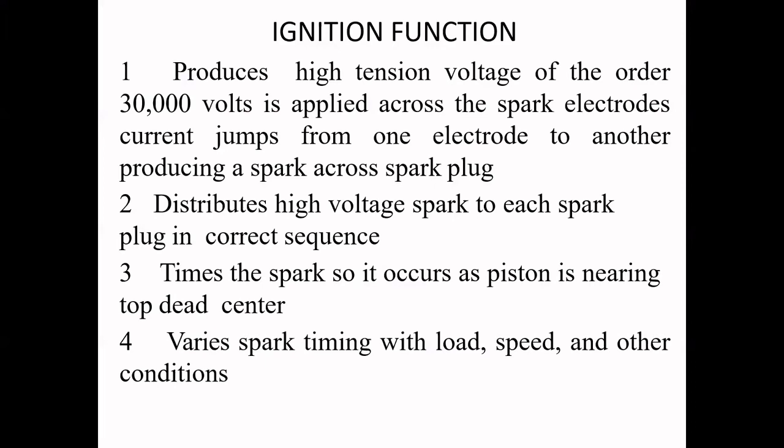So we were discussing the functions of the ignition system, and we know what an ignition system is. Ignition is nothing but the burning of fuel in the presence of air with the help of an external source or with the help of self ignition. Self ignition we see in the case of compression ignition, whereas an external heating element is required in the case of spark ignition.